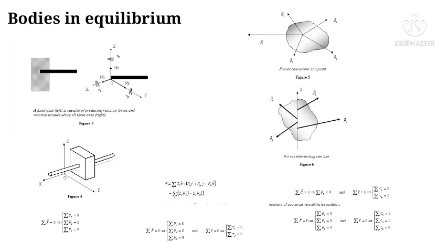Next we discuss what happens if the applied forces are parallel, say to the z direction. Then the forces do not have any x or y component other than the z component, and the torque about z also vanishes. The equilibrium condition in this case is reduced: the summation of Fz equals 0, and the summation of torque in the x direction and y direction is 0. In general, the summation of all forces is 0 and the summation of all torques is also 0.